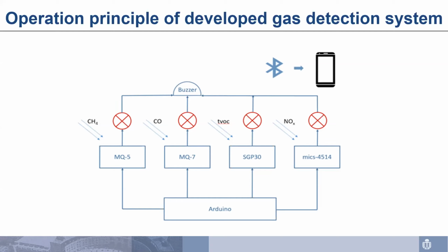If a gas concentration exceeds one of these threshold values, then the system would notify the people, for example, by the respective LED. So if one gas exceeds our threshold value, then the LED would light. Or if any of these cases exceed their respective threshold values, then the alarm would start and notify the people around